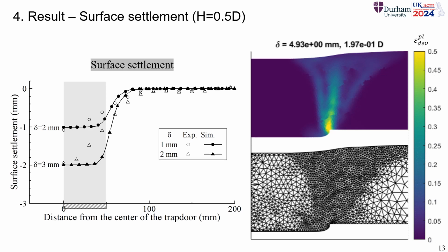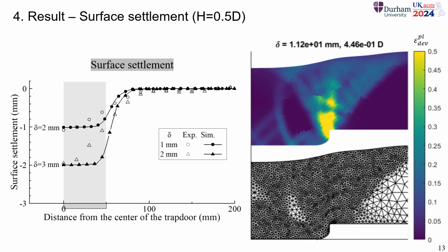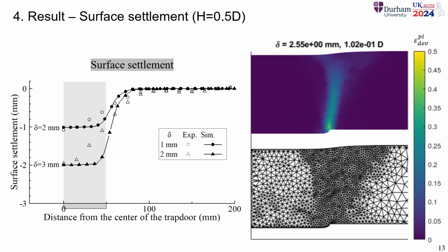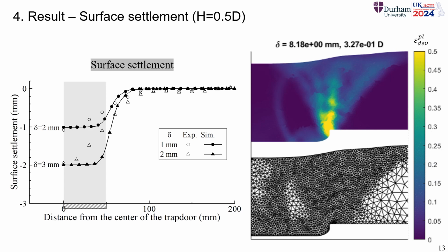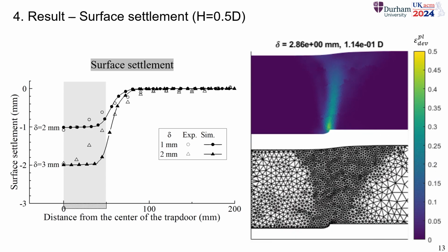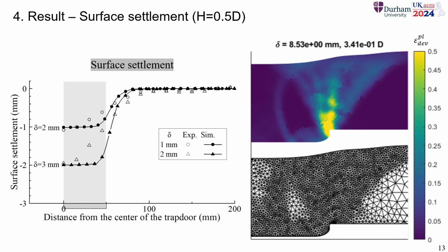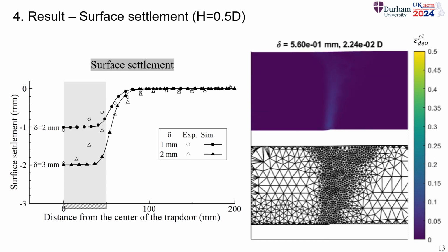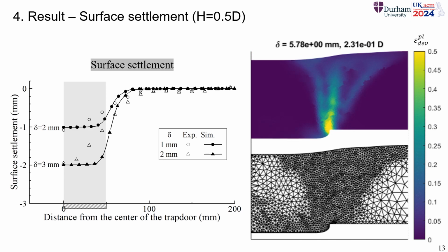While this is shown here with the continuous black dotted line, the experimental results show a much smoother interface, which is what I assume is the reason for the not perfect capture of the loosening of earth pressure during the surface settlement.